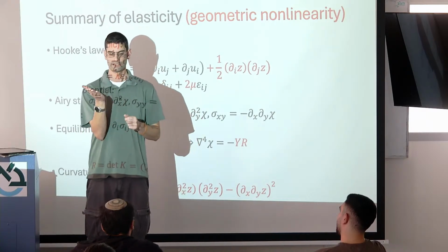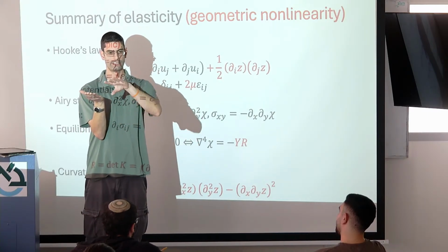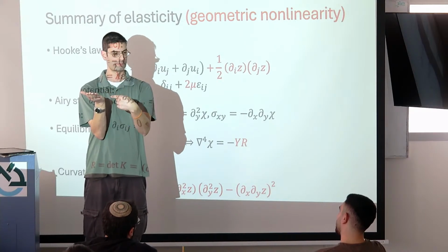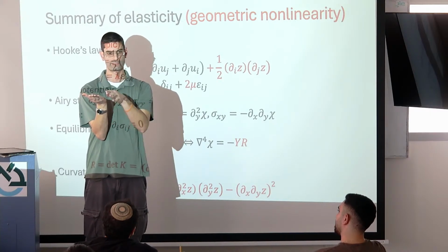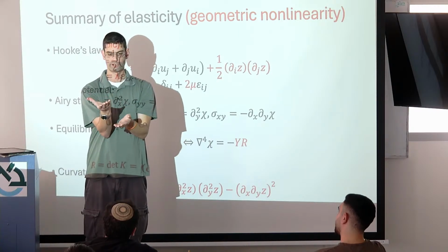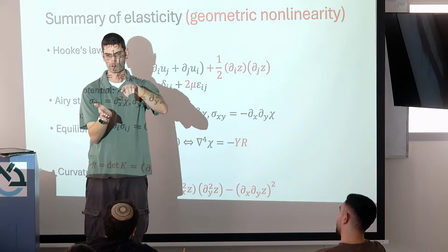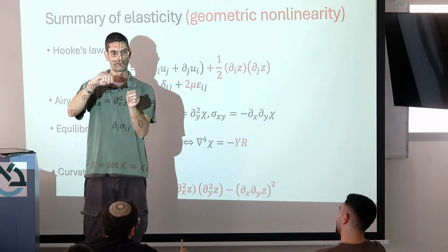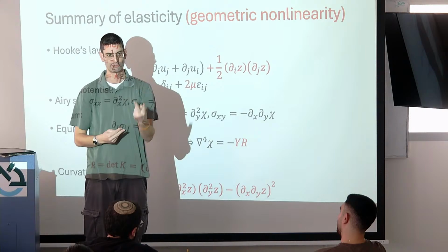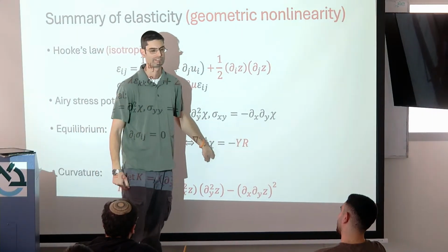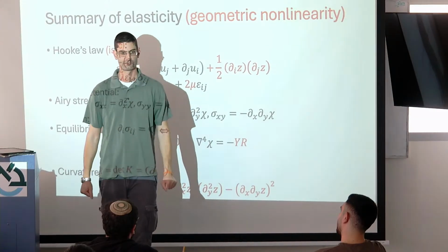So if I allow my pizza to be flat, it can deform with 0 energy, because one dimension remains flat and the other dimension becomes curved, and then my pizza flops. But if I force it like this, then I've created curvature in one direction, and now if it flops, it will have curvature in 2 dimensions, then the product will be non-zero. This will create stresses in the system, and that costs energy.